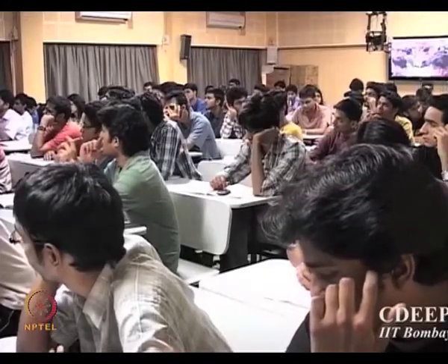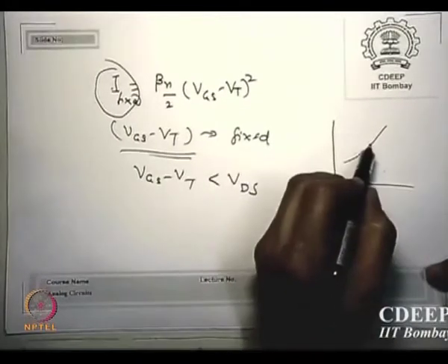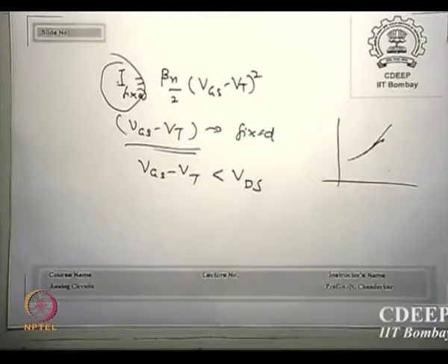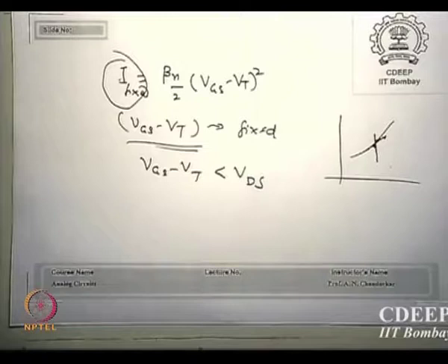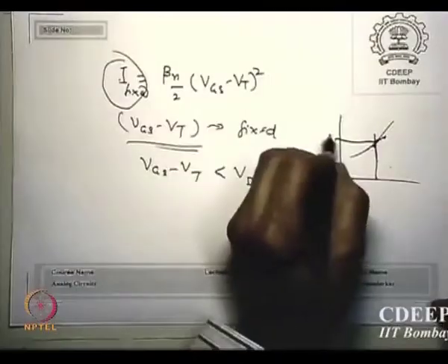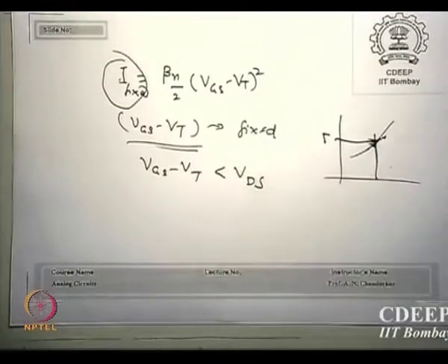But that current is how much? Say I am putting 5 milliamps or 1 milliamp, and this is microamps, 1000 times less or even lower. Is that clear? In any small signal analysis this value is always going to change. You cannot say it's constant, but then how do I calculate slopes? On any curve, I take this value and get a slope here and say, yes, within this small change two values are actually changing. There is nothing I can do about it, but the change here and here is negligible. That is what ACs are all about.